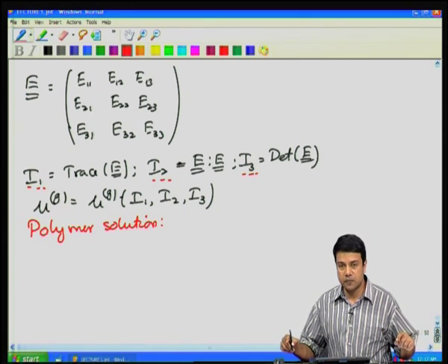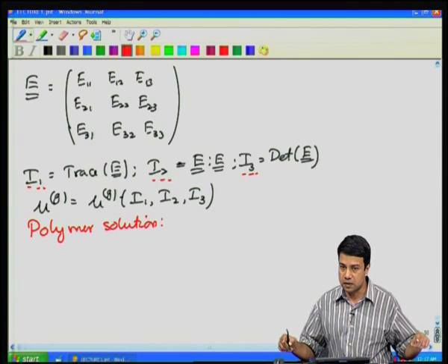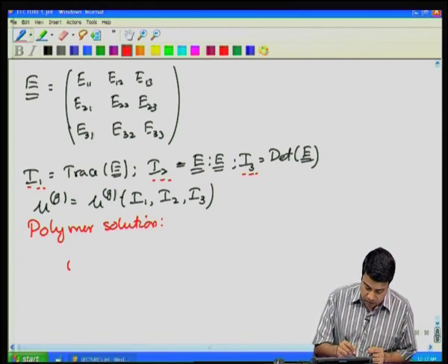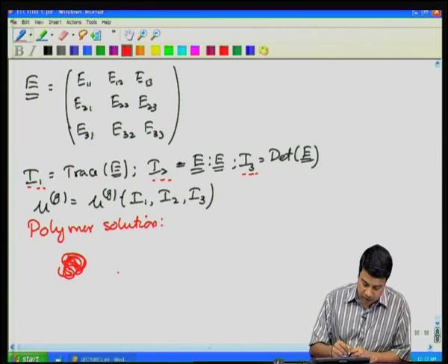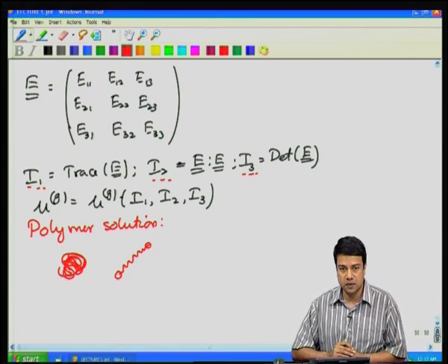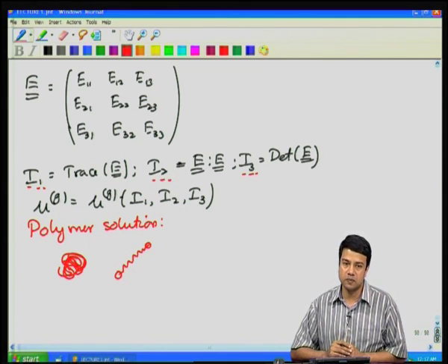However, if you put it into a solution, it is not going to be in an elongated fashion, because the entropy cost of stretching it out is too much. So, in a solution, the polymer is going to be in a highly coiled state. A useful representation for this highly coiled polymer is a bead spring model, where I imagine 2 beads and a linear spring between these 2 beads. The beads themselves represent the ends of the polymer molecule.